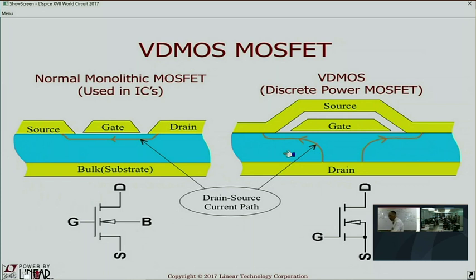Now, if you want to make a power MOSFET, something where a change in 1 volt gate source voltage will give you a change of decades of amps difference in drain source current, then the practical dimensions of that MOSFET is a channel length that might be half a micron and a channel width of 10 meters.